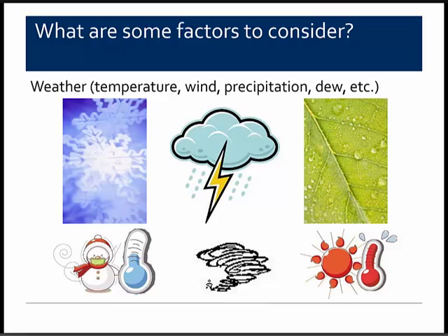What are some of these factors? Weather is an important factor to consider when using adhesives, whether it's the temperature, cold, hot days, humid days, the time of day when the adhesive is used. Moisture comes in various forms, whether it's precipitation, dew, condensation, as well as moisture in existing substrates. The effects of ambient conditions.